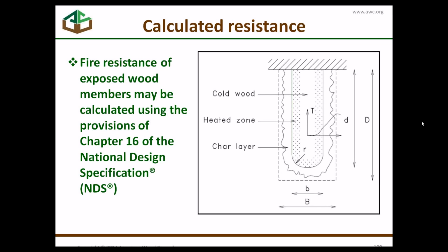There is another method in the code for calculating fire resistance of exposed members. That is back in section 722 in the 2012 code. And that method back there, 722.6.3, will work, but we highly recommend that you follow the main section 722.1 of the code and go to the NDS.